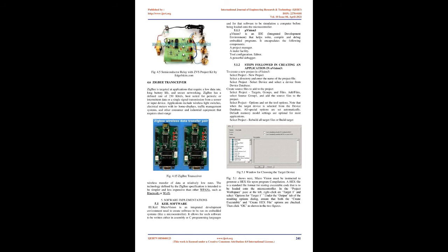The potential transformer will step down the power supply voltage, 0-230V, to 0-6V level. Then the secondary of the potential transformer will be connected to the precision rectifier, which is constructed with the help of op-amp. The advantage of using a precision rectifier is that it will give peak voltage output as DC. The rest of the circuits will give only RMS output.